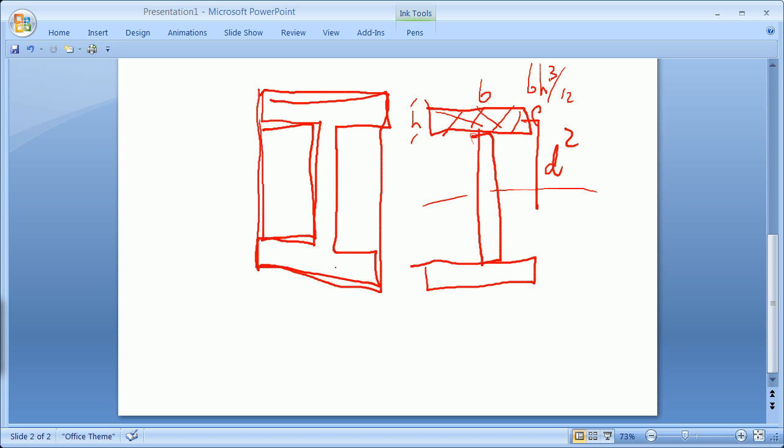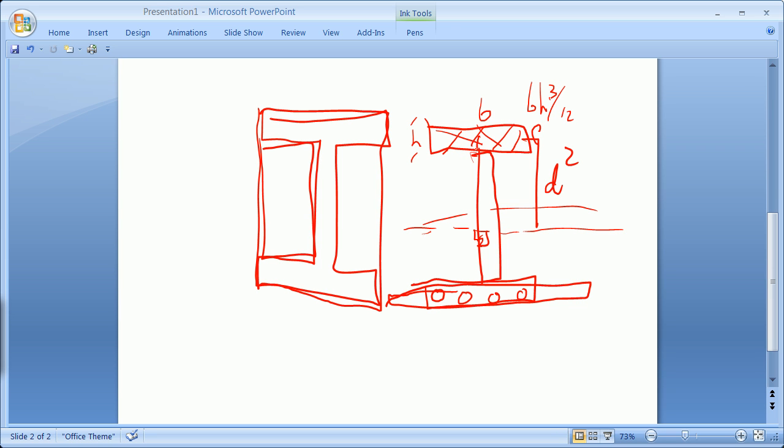How does this work when you put steel? Well, if you've got some steel down here, particularly in the compressive zone, you have to expand the steel, which of course brings down your neutral axis and changes some of that equation of the moment of inertia, which is the sum of all the little areas times all the distances squared. So you've got it, all of a sudden you've transformed the distance in a couple of ways.